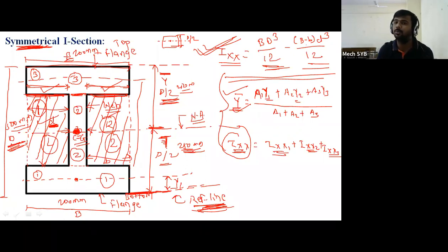Y bar is equal to capital D divided by 2, and you also represent these sections. The two sections that we subtracted, show those two sections with hatching lines in your figure too. Draw these vertical dotted lines and represent those two sections by hatching lines, so that you understand that small b has been subtracted from capital B. Write down both the formulas.